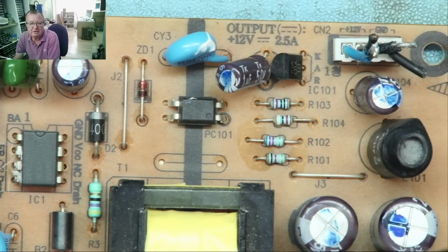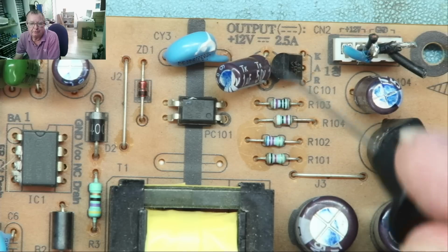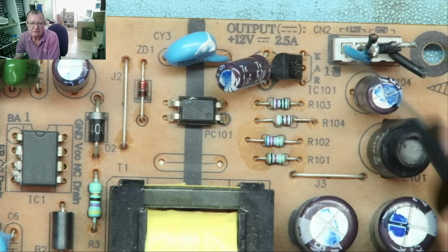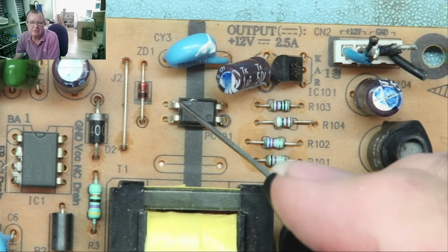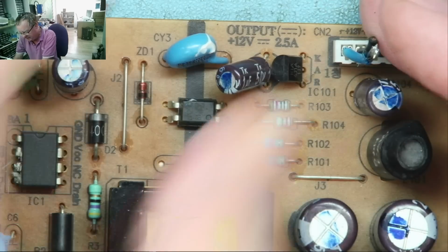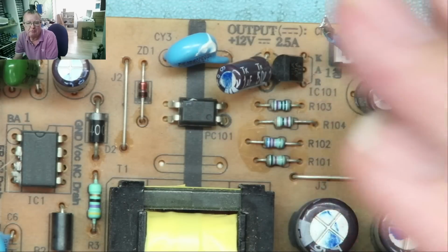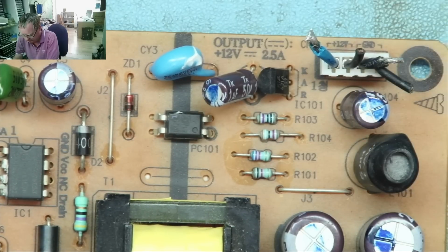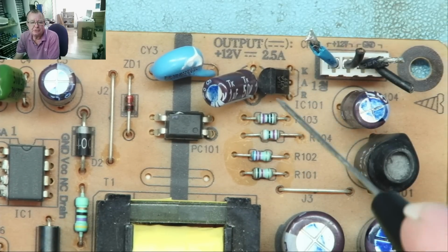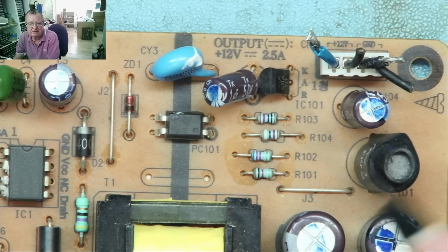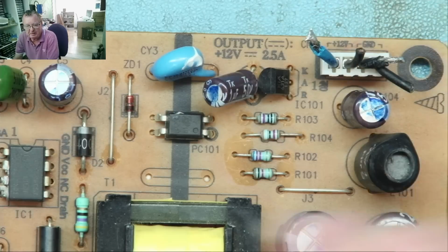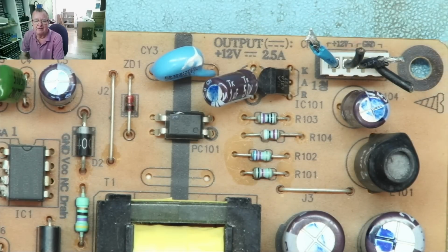Now you can also test this in circuit, the whole thing. So the TL431, the various resistors, the tracks, the continuity, the opto-isolator, the whole thing. And you can do this without powering up the power supply. So I'll show you how to do it. And this is very simple. You can do this on just about any switch mode power supply. And if you suspect the feedback thing isn't working, this is a very good test.